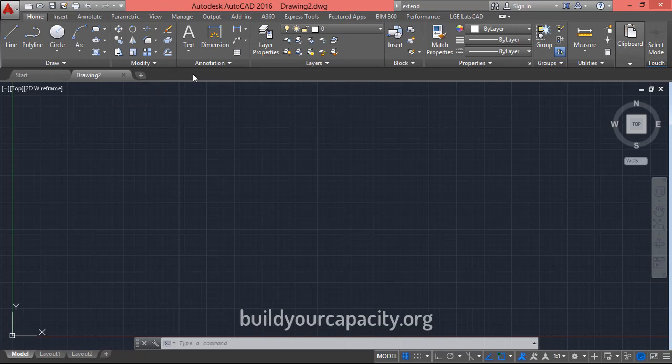You can also keep the expanded panels permanently open by selecting the thumb tag in the lower left hand corner. To make it auto hide, you just click on that thumb tag again and it will now auto hide.